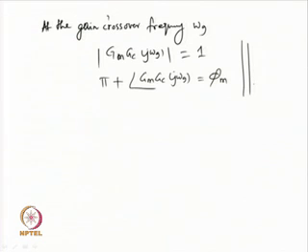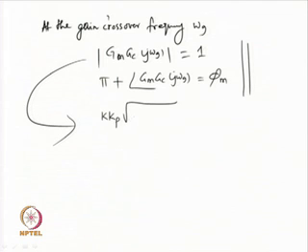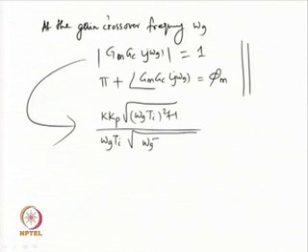So, we shall make use of the analytical expressions you have obtained. Substitution of Gm and Gc will result in the first expression as Kp root of (omega g squared Ti squared plus 1) divided by omega g Ti times root of (omega g squared T1 squared plus 1) is equal to 1.